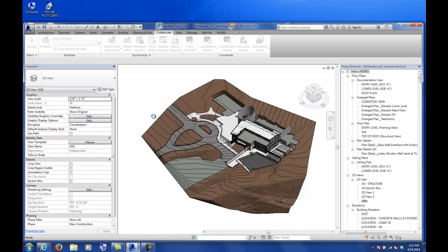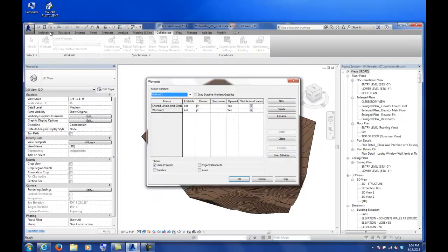And one thing you're going to notice here is it'll take a little minute to generate. But what's going to happen is up here at the top left, you're familiar with seeing that little disk icon, the floppy disk to hit save. You'll know that you've enabled work sharing when you see the wheel spinning. You'll see this other icon will eventually become highlighted. That is going to be an additional save button that is going to be called Save to Central.